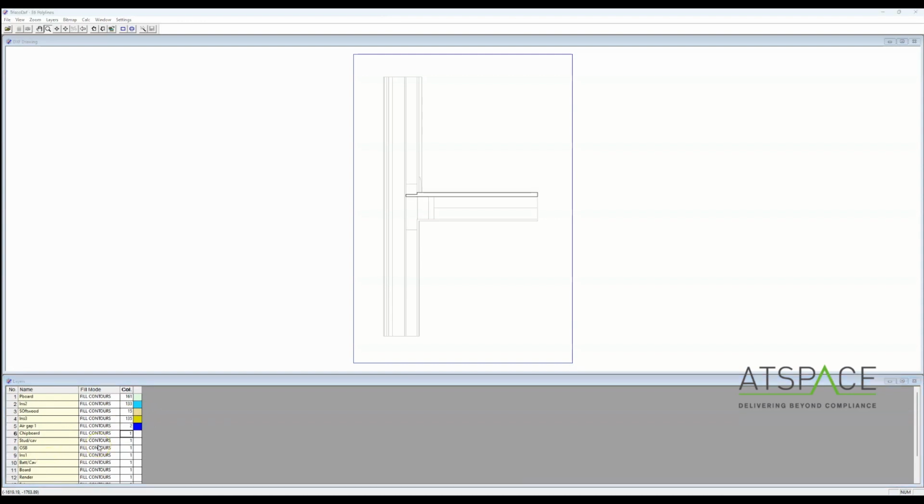And some of the materials are quite specific. For air gaps, which we'll go through in a minute, you have to calculate the thermal conductivity. So there's not really an existing material you can assign for that. So I just go with the lowest number that I know I'm not going to be using for any other materials, if that makes sense.